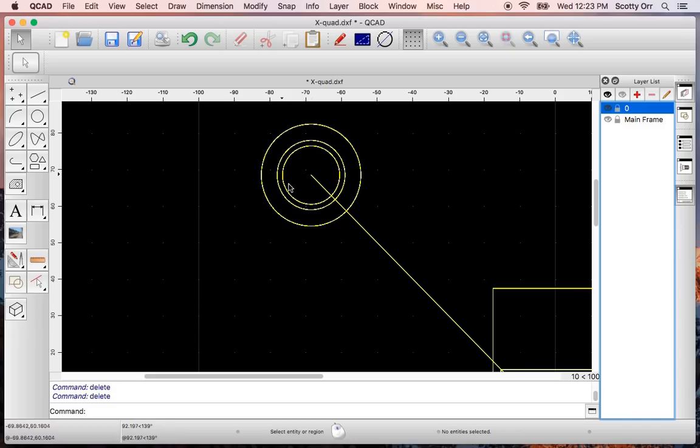Now, this outer circle is 19 millimeters, and I could figure out which ones on my motors are the ones that go where. But instead of making just individual perfect circles for the 19 millimeter screws and the 16 millimeter screws, I'm going to make slots so that it won't matter. So I need to make guidelines so I'll know where to place the circles for my bolts.